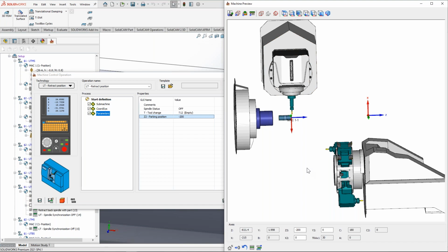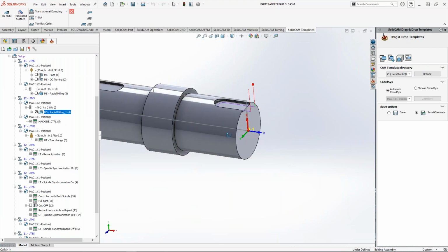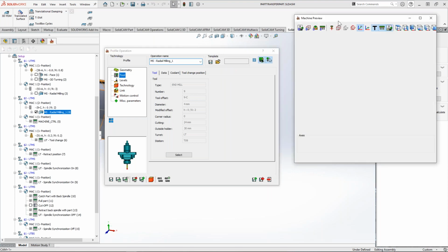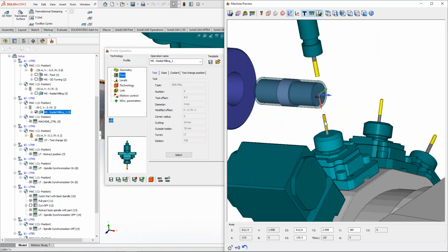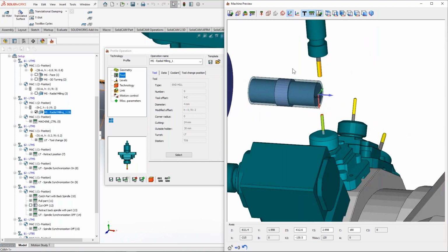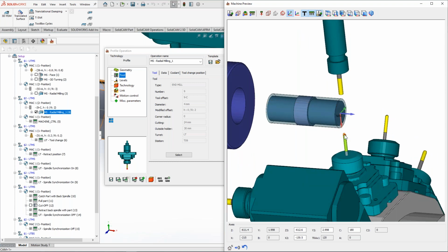Right, I think I passed all that I wanted. Yeah, there's one small thing here that I forgot. So we have here the lower turret job. Let me go here and open it, and it finished the jobs over here. So this is pretty much applicable for the Swiss type machines where you want to move your part inside the guide bush, for instance, or you want to, for example, pre-position your tool with respect to your part in the local coordinate system as we have it here.